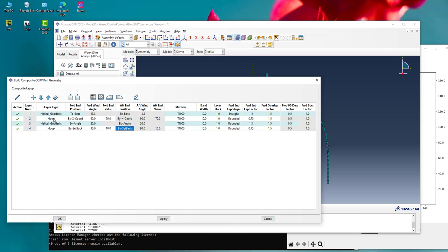So let's say I've got a big long stack of hoops, and each of them sets back a little bit. So I may have 5 or 10 of them that set back from the first one, and then we start the process all over again. So by using setback, we really only have to change this, and then all the ones that are set back from it would get shifted around as we change that one number. All right.